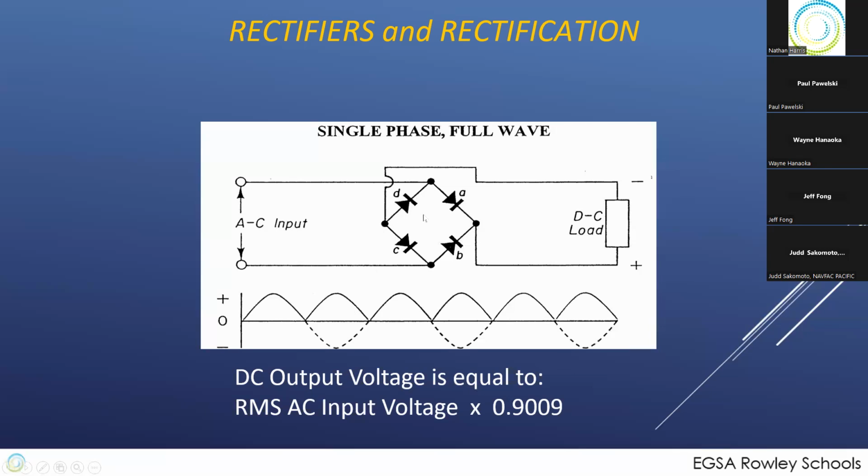Well, that's where we talked about more positive. Okay, if this was 120 volts here, that wire running to the diode has very little drop, so it's about 120 volts here. But here we've got at least 0.7 volt drop and almost certainly a hell of a lot more drop through your load. So that means that this is something under 120. So it's less positive than here, which means it'll go back through this way. And everything runs through in reverse when this becomes the positive one.